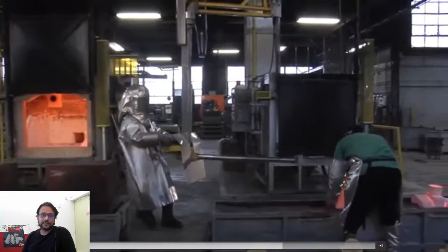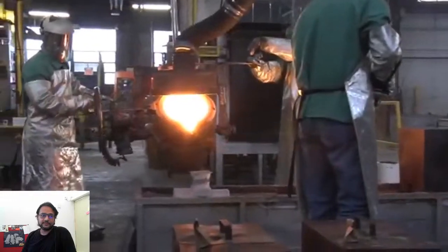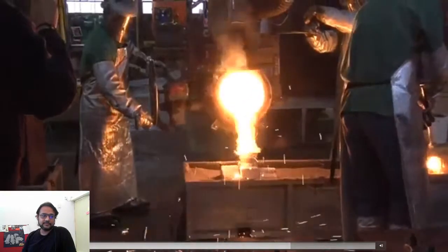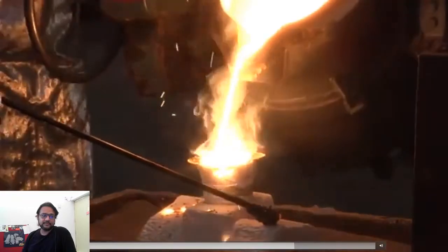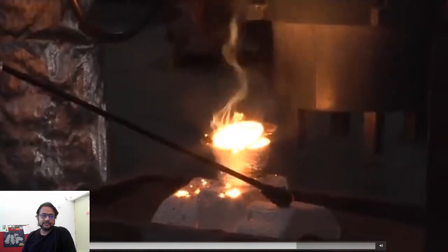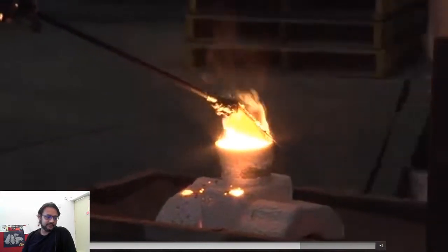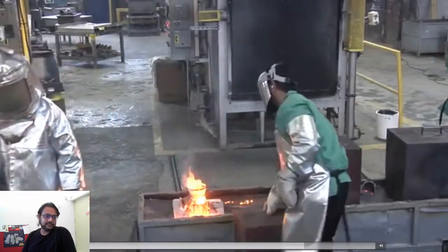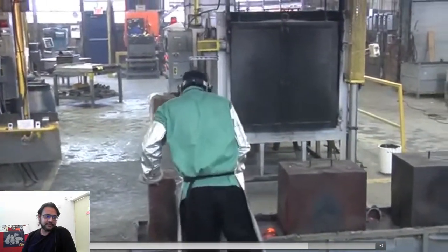While the shells preheat, we prepare and melt the metal to be cast. When at the proper pouring temperature, the chemistry of the alloy is checked, and the molds are filled with the molten metal. The metal completely fills the cavities of the mold, taking on the geometric shape which will form the outer detail of the cast component. Inside the cavity, the molten metal also surrounds any cores, which will impart the same detail to the internal geometry of the casting.